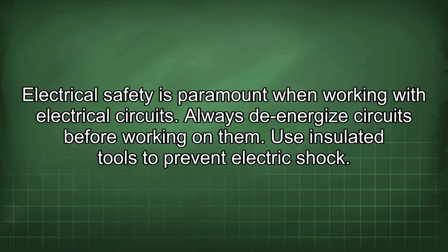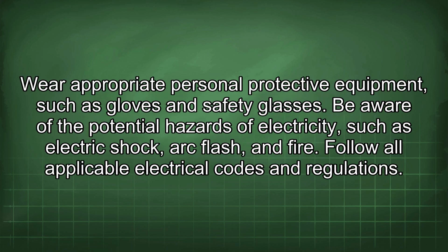Electrical safety is paramount when working with electrical circuits. Always de-energize circuits before working on them. Use insulated tools to prevent electric shock. Wear appropriate personal protective equipment, such as gloves and safety glasses. Be aware of the potential hazards of electricity, such as electric shock, arc flash, and fire. Follow all applicable electrical codes and regulations.